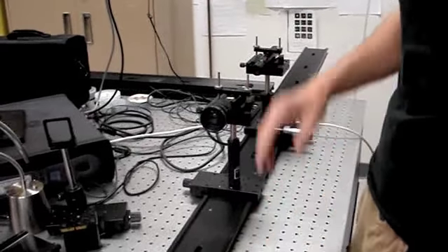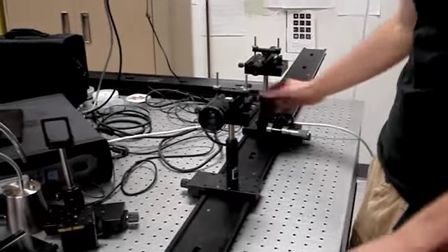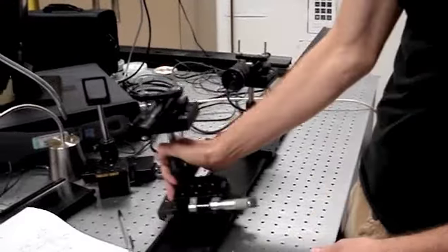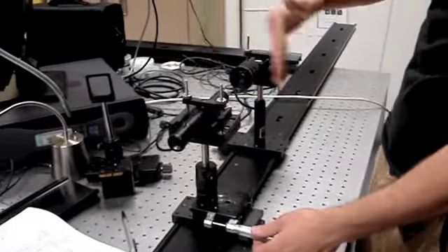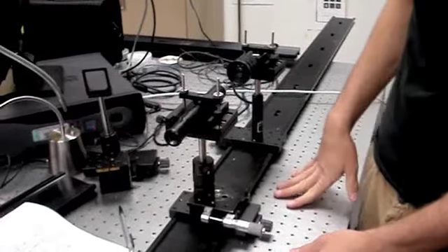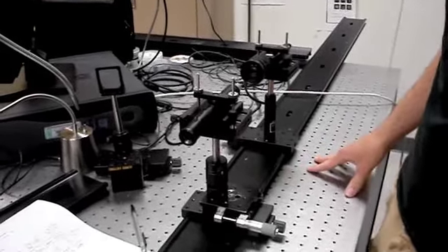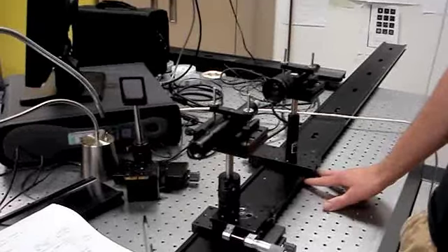We also wanted to know the size of the pixels, so we took off the lens, so we're just seeing the detector, and we put the microscope in there and used that to measure the height and width and divide by 480 and 640, which is the number of pixels, and determined that our pixels are 10 by 10 microns.